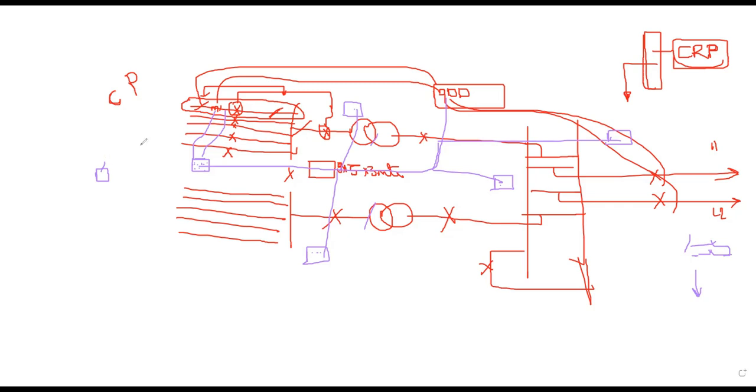But now, with the concept of BCU and BCPU, this hard wiring is reduced, because the BCU is an intelligent IED where you can take the status of the breaker, the status of the isolator, and here you can write a program.